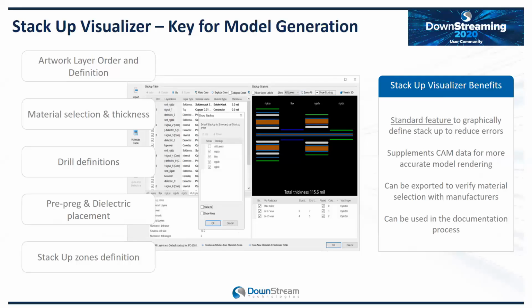As you all know, if you're outputting Gerber files, unless you have really strict standards, a lot of people will just output all your Gerber files as GERB1, GERB2, GERB3, GERB4, or ART1, 2, 3, 4, etc., without putting specific names on it. So when you read that data into CAM 350, or really any manufacturing tool, you have to spend some time to tell the system what file is actually what layer, what it's related to in the stack up. And that's typically done for any 2D visualization, but it also is integral for 3D visualization as well.